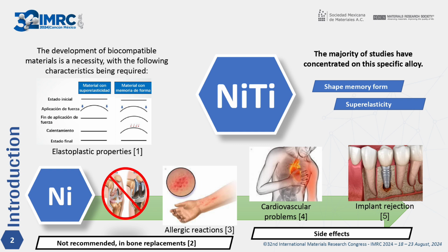high standards of biocompatibility. Shape memory alloys, or SMAs, are defined as those alloys that have the capacity to revert to their original shape following deformation. This phenomenon is attributable to the shape memory effect, which is induced by thermal or magnetic changes. One beneficial aspect of this phenomenon is that the deformation can be replicated repeatedly without any deterioration or damage to the material. This behavior is sometimes confused with that of superelastic materials. However, while there are similarities, they are in fact quite distinct.